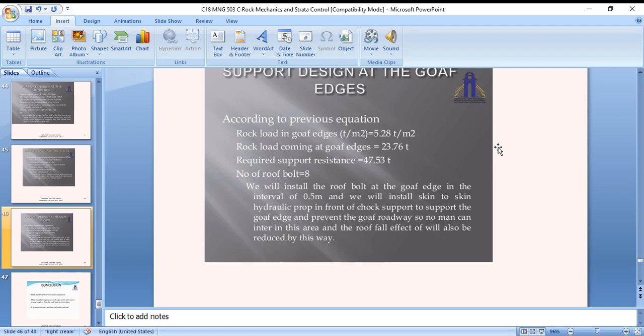From the load, the factor of safety is double that one. So for example, if 50 tons, then 100 tons is required. For 100 tons, how many roof bolts are needed is found by dividing by the capacity of each support. So that will be planned in such a way that the exposed area and ESR, excavation support ratio, according to which we design the support systems. This is the overall idea of RMR versus rock excavation exposed area and support parameters. So these three you have to use scientifically and methodologically.